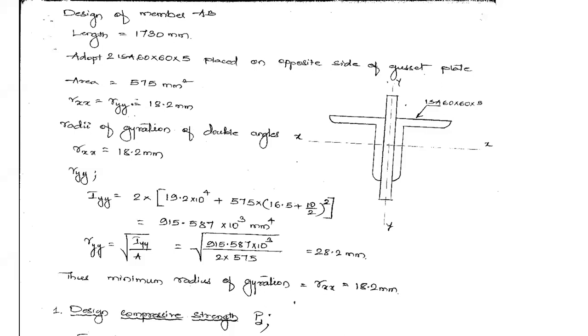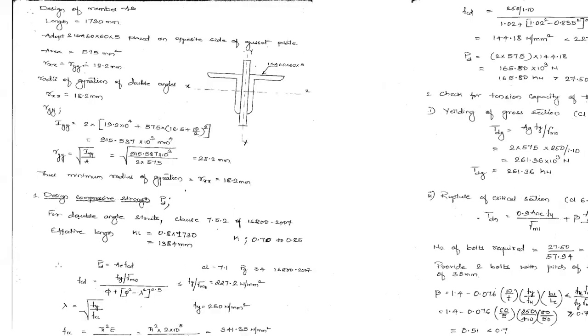What you need to do is look at the connection first. One, it should be able to accommodate the bolt hole in it. The second is the member length and the force in the member. That has to be given consideration. So as a trial section, you need to decide on this basis.